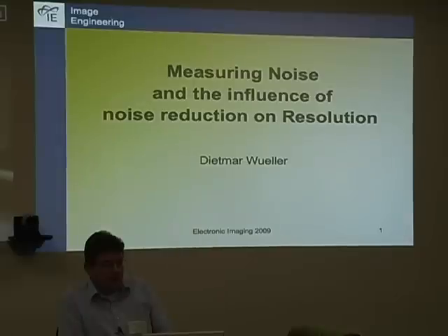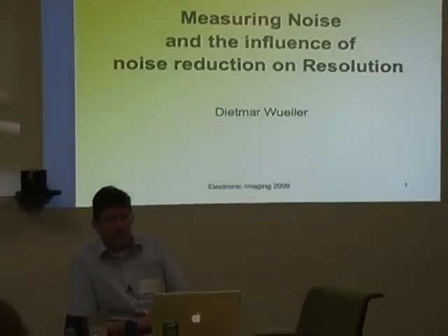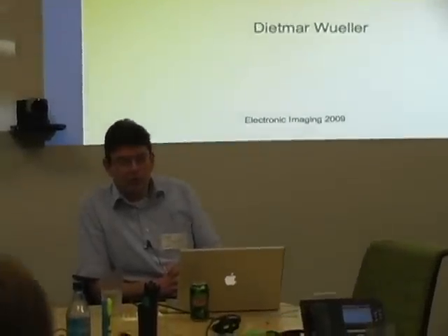So they want to keep the sensor size on a very small level, and then, of course, noise of the signal is more visible. And they try to get rid of that noise using image processing in their cameras. The way they're doing that, of course, also leads to a reduction of especially something we call texture, which is low contrast fine detail.